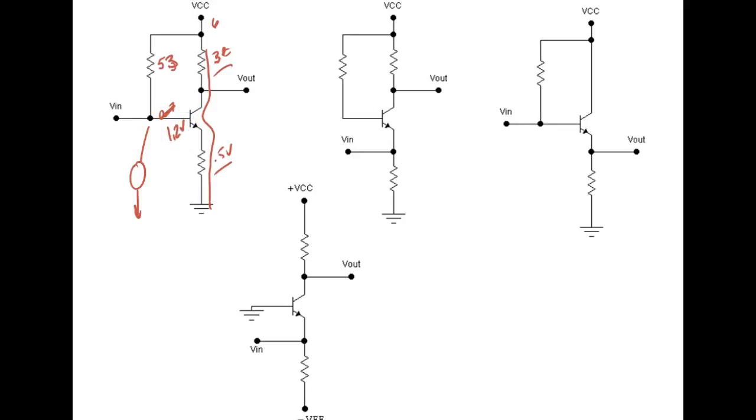I understand we're working back through here backwards. If this is 0.5 of a volt, how much does this guy right here drop? 0.7. So that means relative to common, the base is going to measure what now? 1.2 volts. And then this resistor right here would be dropping the rest. What would that be? 6 minus 1.2 is going to be what? 5.8. No, 4.8.